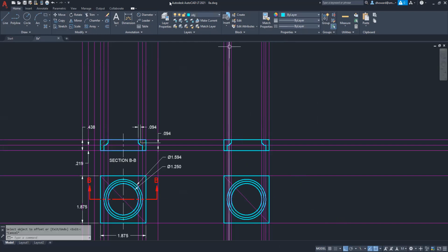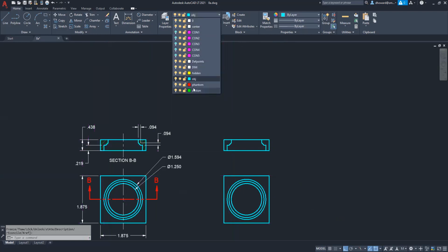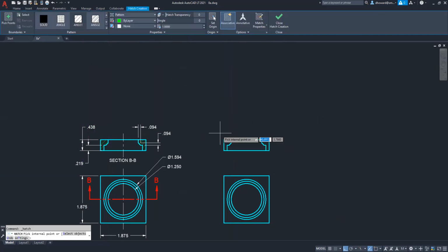Okay, the last thing you want to do here is turn off your construction lines and drop in your hatch marks there. So just click on hatch and grab this area. And I made mine, I think, a bit smaller, 0.9, 0.8, something to get some more lines in there, 0.7, maybe 0.7.